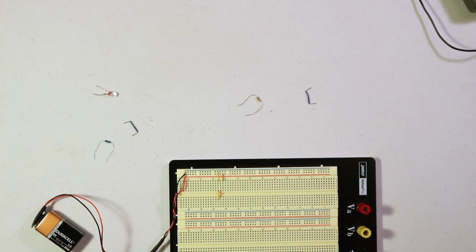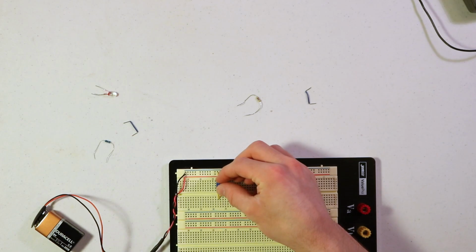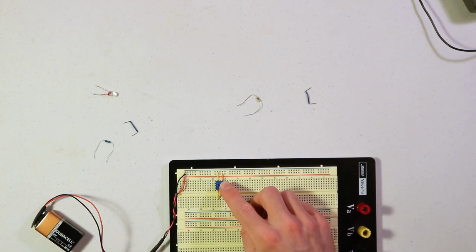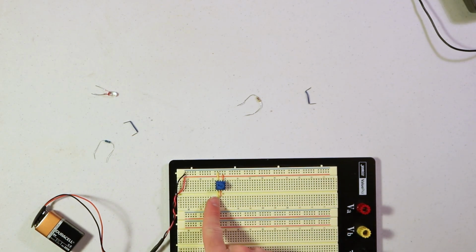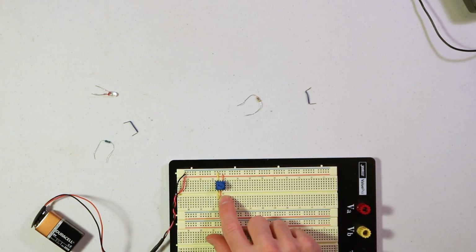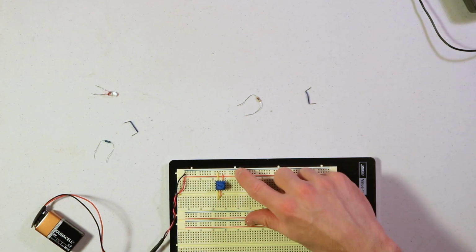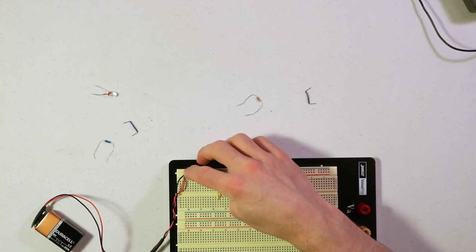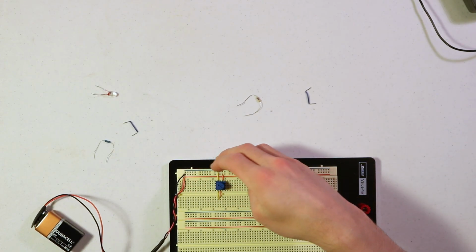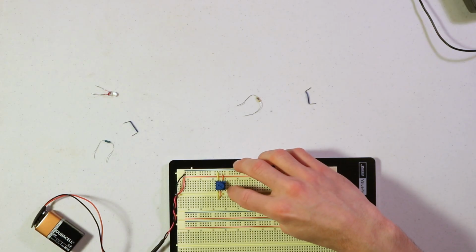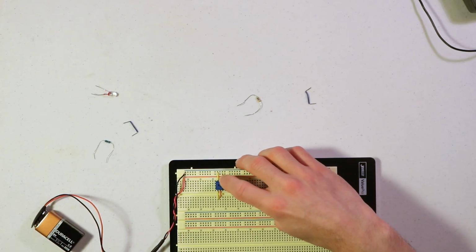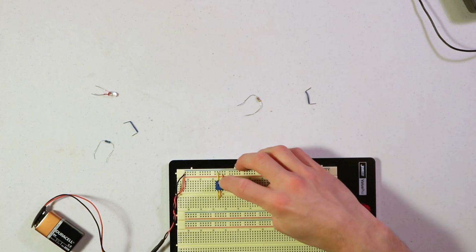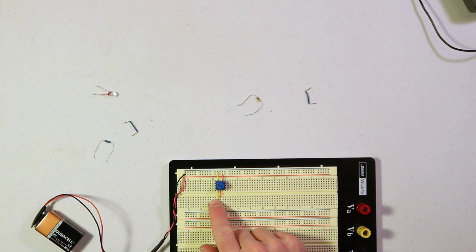Okay, so just put those ones in there, and then you can plug the potentiometer back in so that you have, say, the left pin here connected to these yellow wires, and then the middle pin connected to this orange wire, and the far right pin connected to that orange wire. So we have the positive voltage coming in here and going through to this side, and then the negative voltage coming to the negative line, going through the potentiometer and coming out here on this negative one.